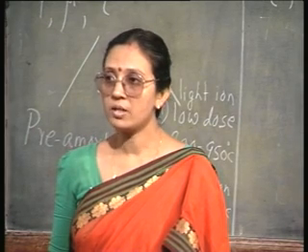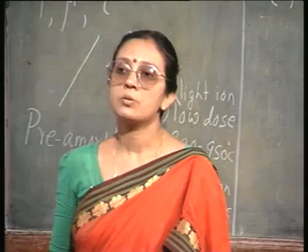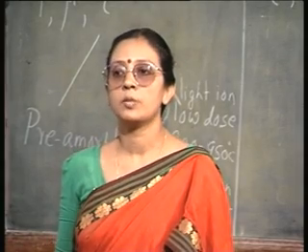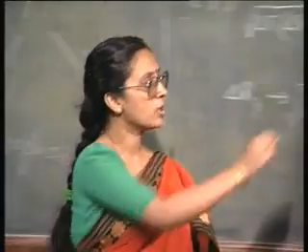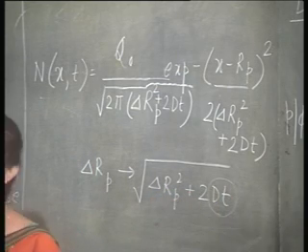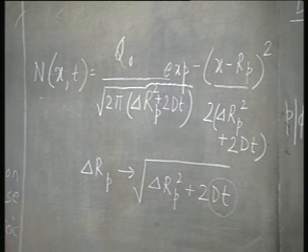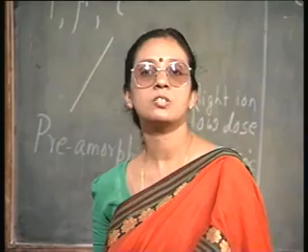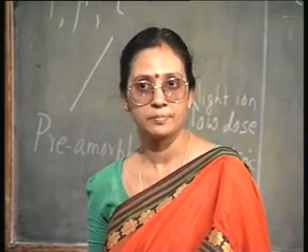Okay. So, the advantage is that there is absolutely no change in the doping profile. You see, this t, you are keeping extremely small. So, even when the temperature is large, the product Dt still remains very small. Therefore, the dopants do not have sufficient time to move inside.